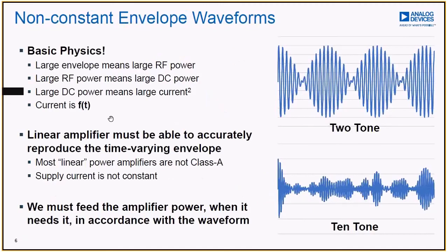So before we get into the next couple examples, I want to point out something that we often forget. If we're doing CW waveforms in an amplifier, that's a pretty simple problem for the bias network to handle. It has constant voltage, constant currents. Nothing is changing.